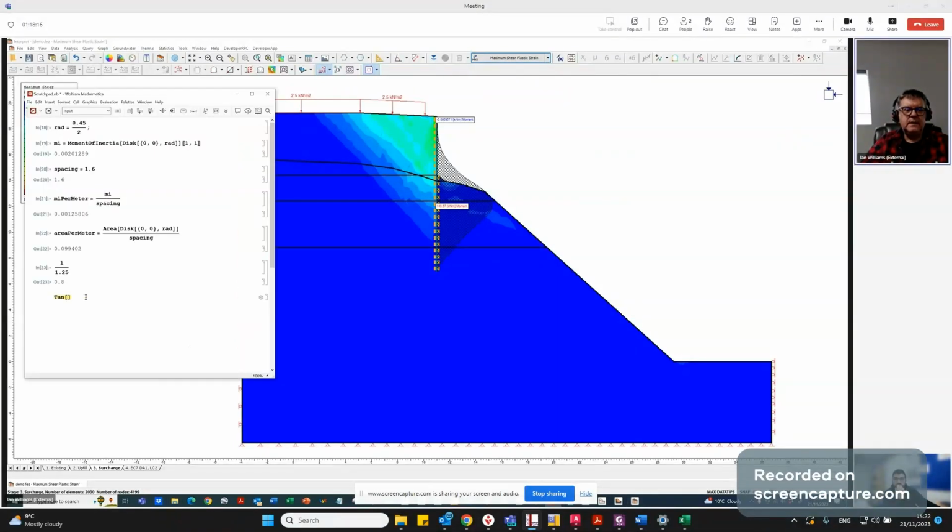So tan, well, that's fine. It's tan 38 degrees. What was the factor again? 1.25. So we can put that in, and then we want arc tan of that. And that will indicate what's going on, based on our engineering. So we've undercooked it. At the minute there's no testing at all. So that friction angle, for example, should have been 32 degrees.